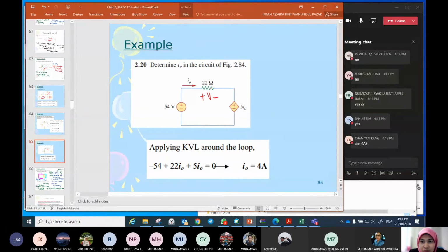There is no negative and positive for a resistor. This positive and negative is the polarity for the voltage drop across the resistor. So when there is no notation of voltage drop across that resistor, we just assume that the voltage drop across that resistor is positive and then negative. So when current flows through the element, the voltage drop is positive then negative. Can you understand?